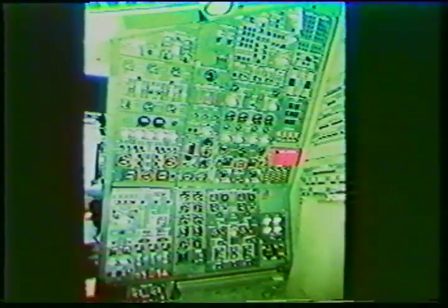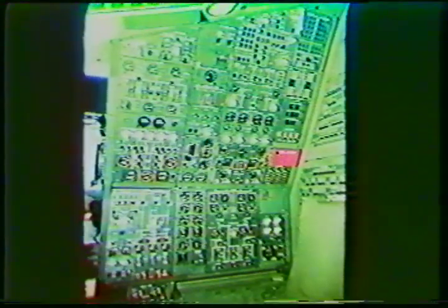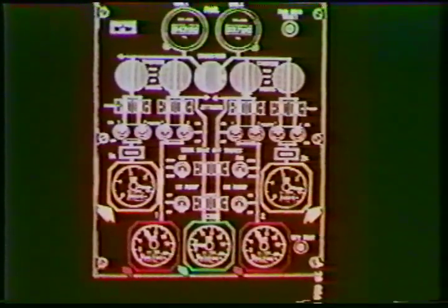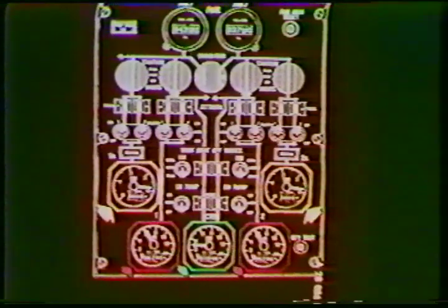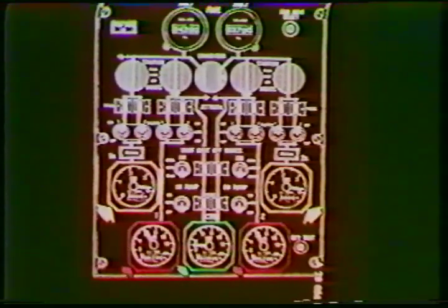Fuel management is accomplished on a control panel at the second officer station on the flight deck. The control panel reflects the flow of fuel from the tanks to the engines and APU, scanning the panel from the bottom to the top. At the lower part of the panel are 5 fuel quantity indicators numbered from left to right, 1A, 1, center, 2, and 2A. They correspond to the location of the 5 fuel tanks.